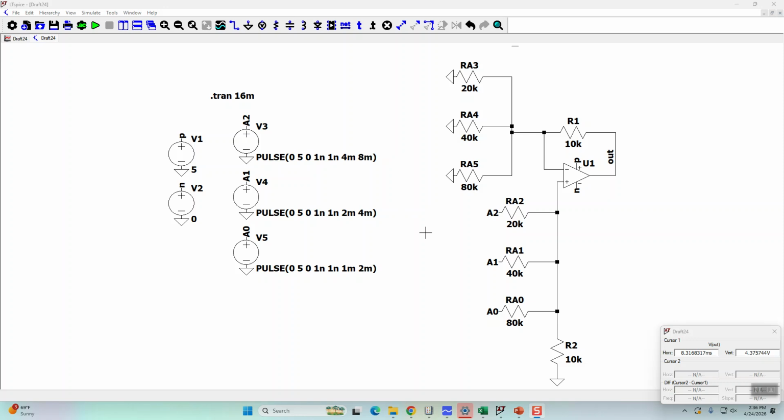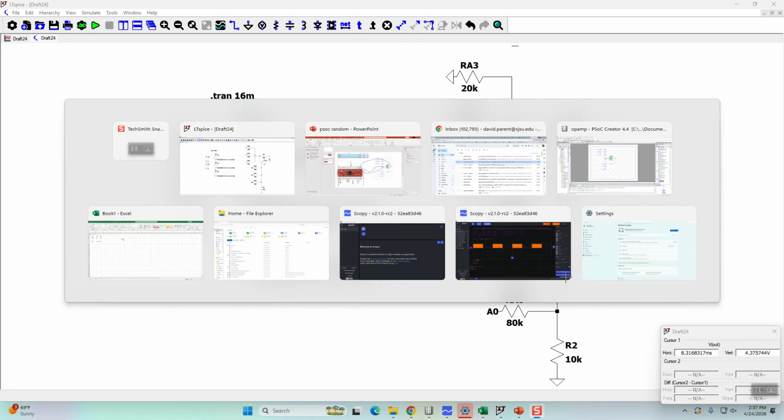And this can be done with an advanced summing technique, which isn't covered in EE98, but it is in 110. I have a whole manual on how to do this. But essentially, if this number here, 10K, is the same there, and you take the ratios of 10K divided by these and sum it, and take the same ratio here and sum it, and if it equals the same thing, it all works out. Kind of hard to derive, but easy to use.